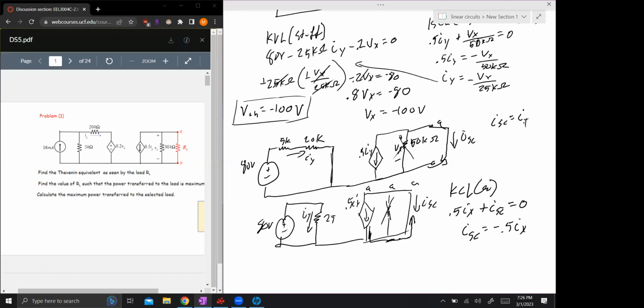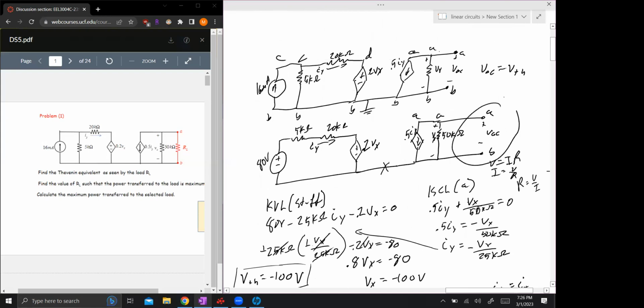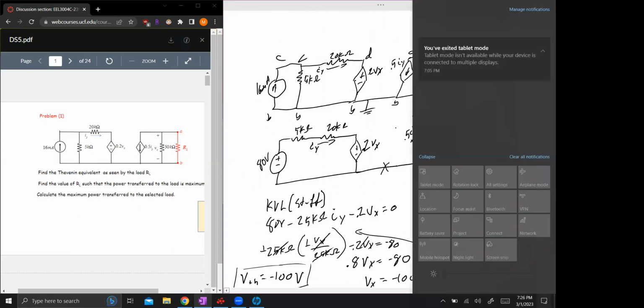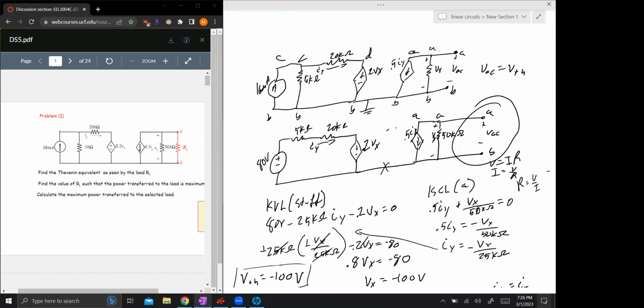Sorry, quick rewind. For just we're dropping all dependent voltage sources. No. What we're doing, there's two ways you can find Thevenin resistance. The first way is to leave this side over here as an open circuit, and then you remove all of the independent sources from the circuit and calculate from there.